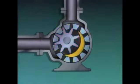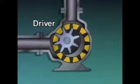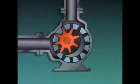The spacer prevents liquid from flowing from the discharge back to the suction of the pump. On this pump, the outside gear is rotated by the pump's driver, so it's the power or driver gear. The inside gear moves because its teeth are meshed with the teeth of the driver gear, so it's the idler gear. But keep in mind that on some internal gear pumps, the inside gear is the driver and the outside gear is the idler.